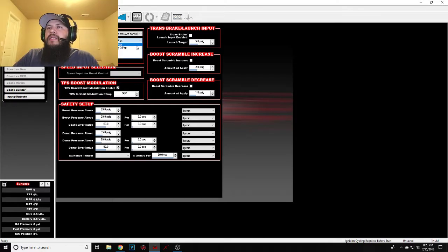Okay, so this is Holley's preferred method of boost control. I don't really like the dome control thing, but I get how it works. It's just as usable as using the MAP as reference. Then it's going to ask you your solenoid configuration. Single Holley 3-port, or these are just types of 3-ports. I don't actually know whether the Humphrey is normally closed or normally open. Maybe that's the only reason they show it as a difference. But the Holley 3-port is a MAC solenoid. It's a MAC 3-port, same as pretty much every other rebranded solenoid that people sell.